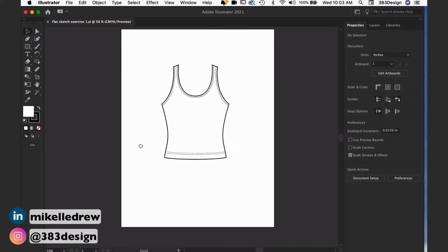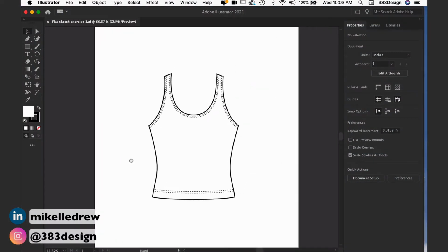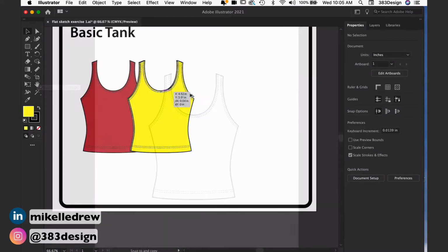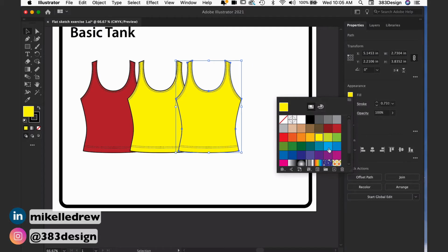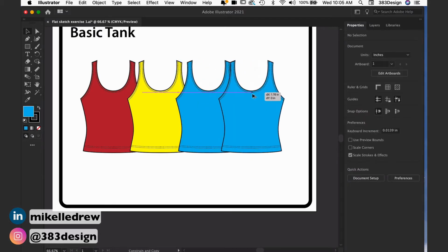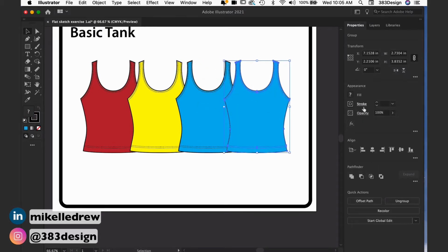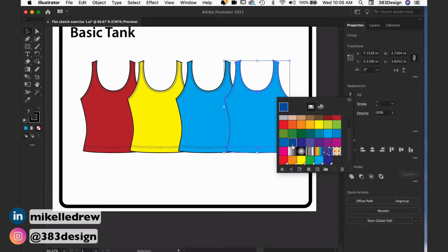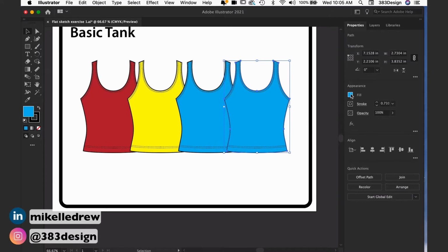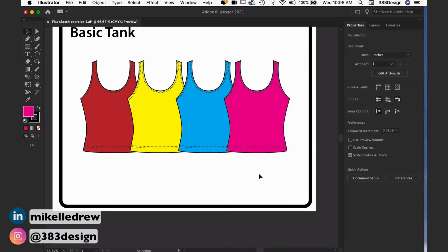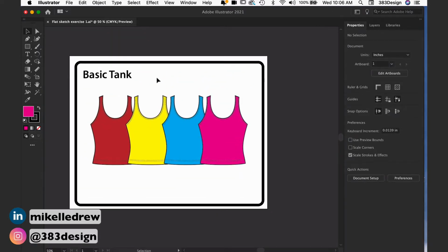For most of us who use Illustrator for fashion design, you're not only drawing a black and white fashion technical drawing, but you're also filling it with color to show the style in all the colors it's offered in. Most people refer to this as a color CAD. So one of the main reasons you'll hear people talk about needing to create a closed shape when you draw your flat sketch is because the sketch won't fill properly if it's not closed.